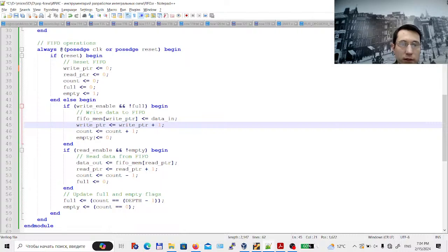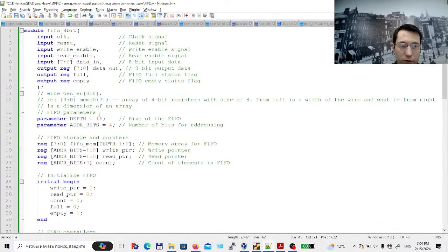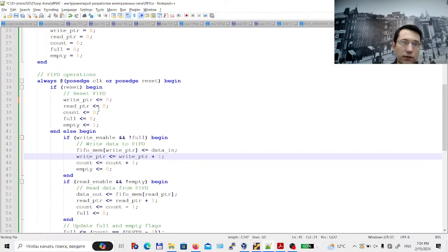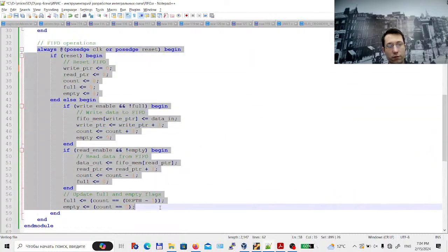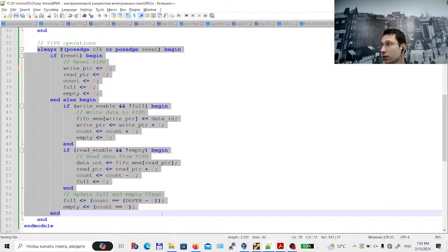So as you can see, it's like C coding. In Verilog we don't need to write every possible state or connect each wire. It will be automatically generated using those expressions.